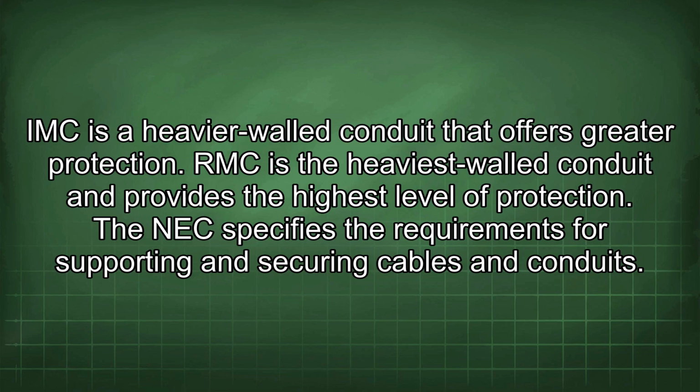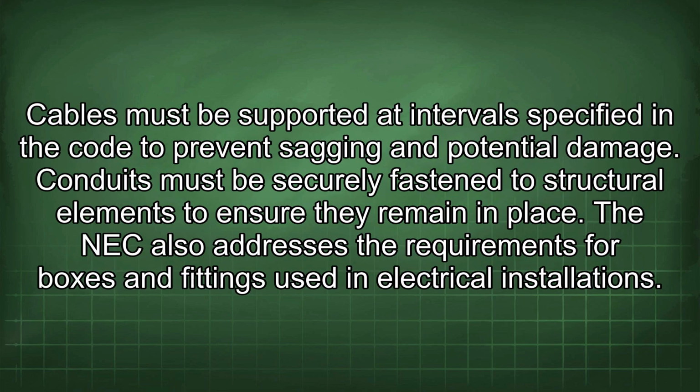The NEC specifies the requirements for supporting and securing cables and conduits. Cables must be supported at intervals specified in the code to prevent sagging and potential damage. Conduits must be securely fastened to structural elements to ensure they remain in place.